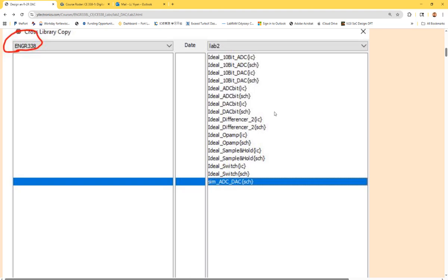You'll see the circuit in the tutorial later. But anyway, we put the ADC and DAC together as a circuit, and we want to simulate that circuit. So then you need to create another schematic to simulate it, because all the simulations happen in the schematic. You put a voltage source over there, and you write your SPICE code at the bottom.